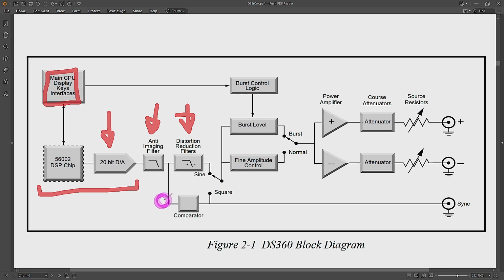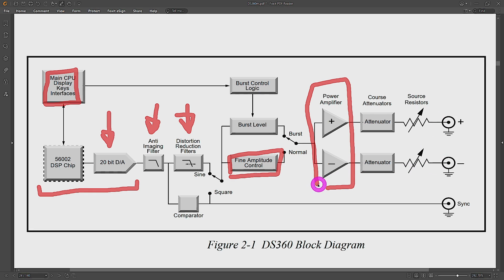There are limitations here, and that's why this instrument has only a certain frequency range and so on, and this is not so easy to do at very high frequencies, especially as the frequencies get higher and higher and harmonics move further away. But this certainly gives you that really high 110 dB or so of dynamic range. But the job isn't done here yet, because you need amplitude control and everything else. So there is some fine amplitude control circuitry based on some op-amps that they have built there. And after that, they have these power amplifiers for both the balanced and unbalanced output. These are basically independent parallel amplifiers made of discrete components with a very high power supply and a really, really high output THD improvement that you can get over the entire system.